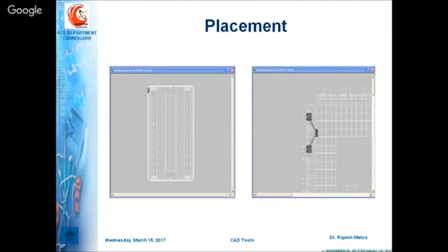So in this way, floor planning plays a very important role in placement and routing, right? So all these things are very important. So you place your circuit. Once your circuit is placed, the next part is that you have to make the final connections between the different components you placed over the CLB or PLB, on the silicon area. Here again, this is the routing part, on the left-hand side, and here you can see the zoomed part where your circuit is placed,